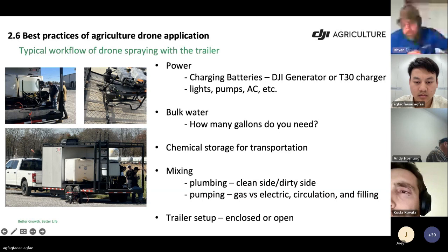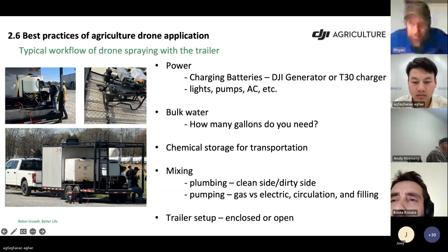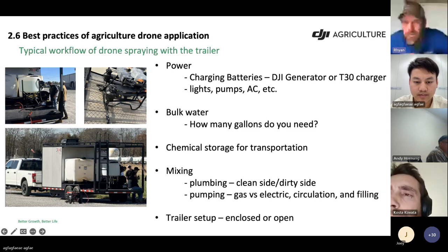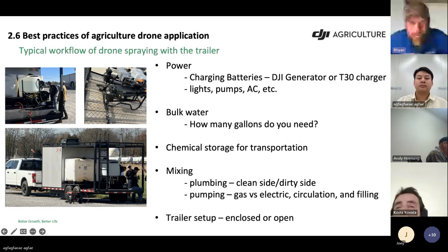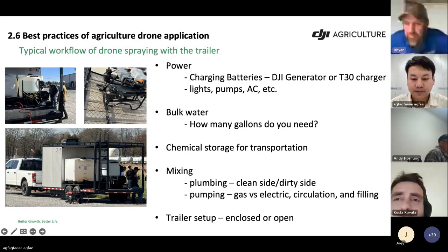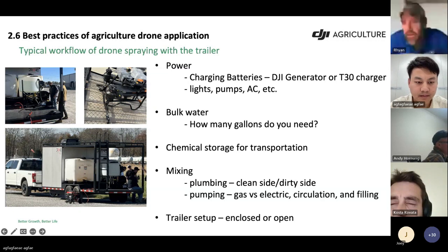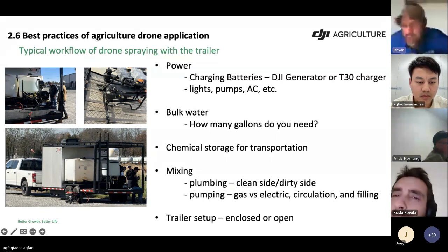Excuse me. I personally am not a fan of auto shutoff valves. Using your diesel or DEF or gasoline auto shutoffs, I'm not a big fan of those. They kind of pull heavy on my fill-through cap. I feel like they start to mess with the calibration on the weight sensor module on that side. I also feel like they induce air into my chemical mix and I get a little bit of foaming in my tank that I'm trying to avoid. So for me personally, I prefer a banjo ball valve with a filler neck on it, and I just turn it on and off that way.